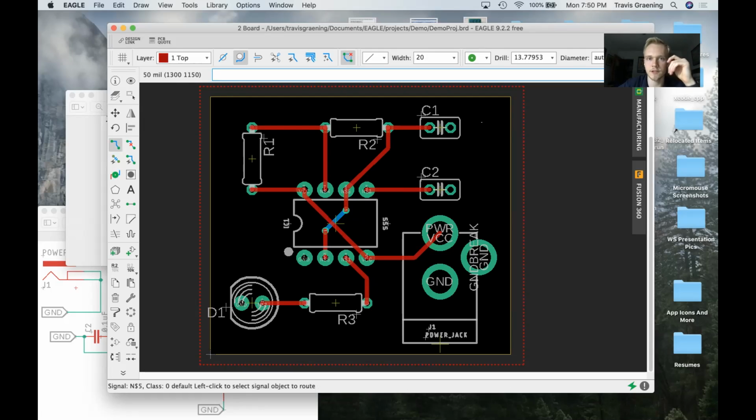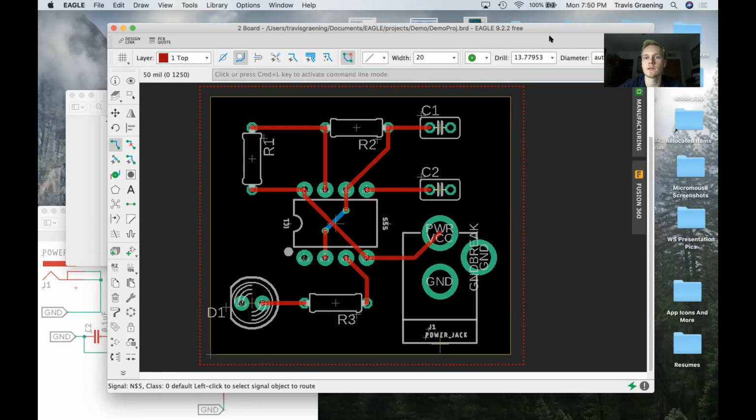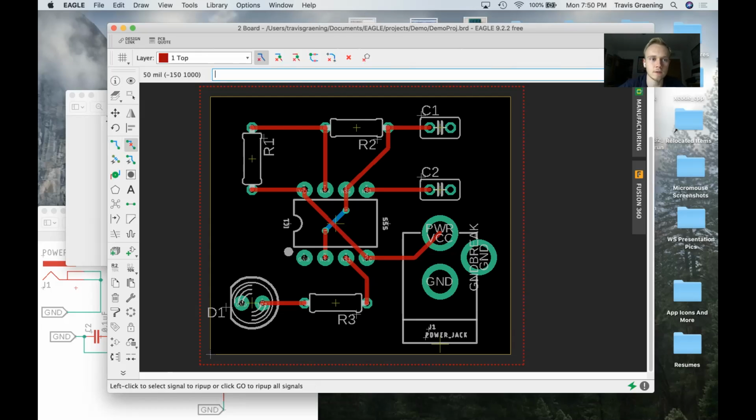It's a very useful feature of Eagle to get from one layer to another. All right, fantastic. So let's do our final step, which is our design rule check, and we'll see if any errors cropped up. Delete routing. Yeah, sure. That's the rip up button right here. It's right next to the routing button, and it has a little X over it. So you can just click rip up, and it will get rid of your routed trace.